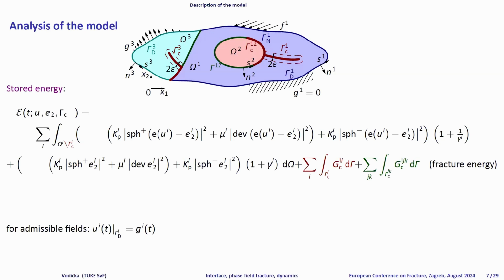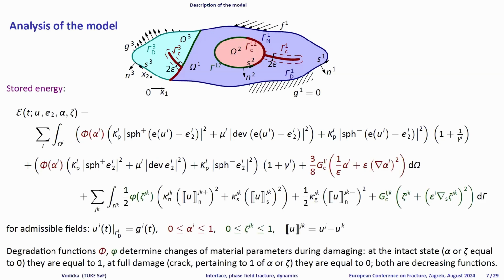With the phase field model, we replace those integrals, also on the interface, by regularized integrals, which instead of having unknown contours, unknown cracks, introduce a new additional variable in damage fashion, which is called either the phase field damage parameter or the interface damage parameter. So we have these two regularizations, which have a very similar form.